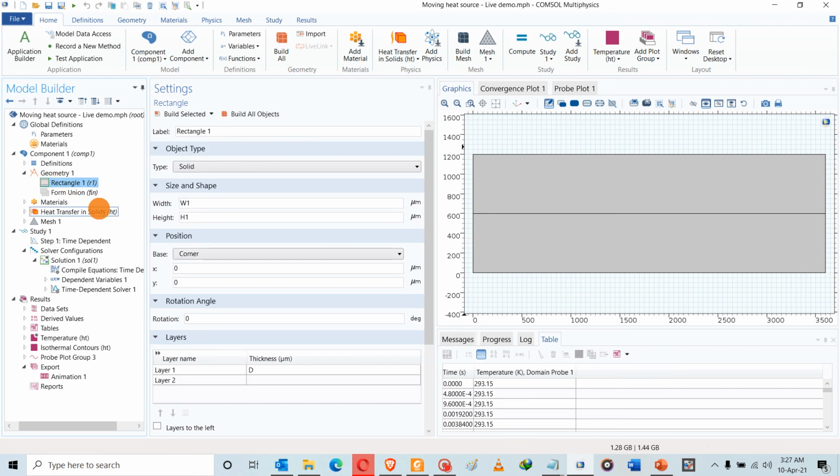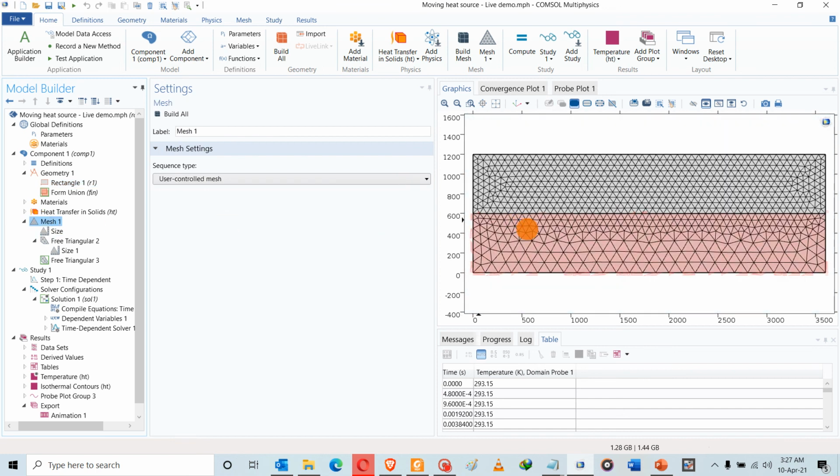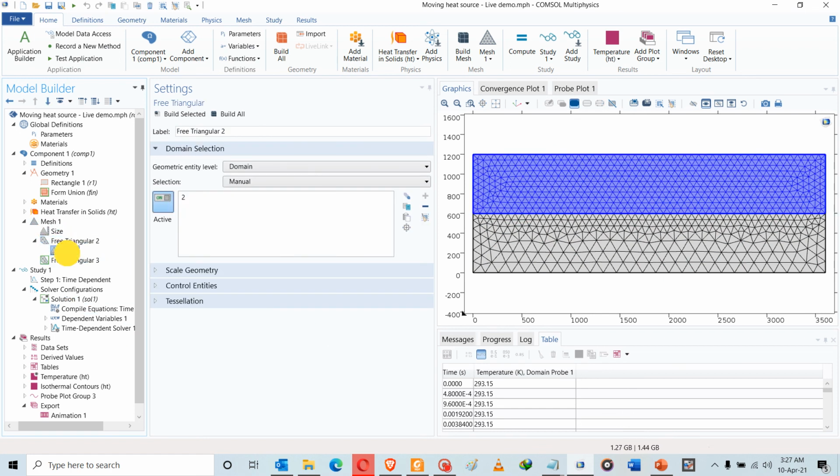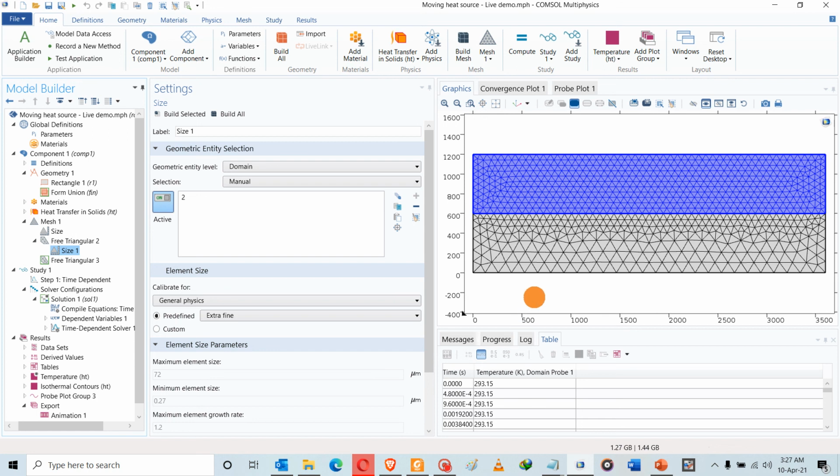And then this was our sample. We created two layers, where the top layer is highly meshed, and the bottom layer is not as highly meshed, with a coarse mesh. We had to modify this mesh from a very fine mesh into a coarse one to have a much quicker computational time. So in a way, this is a way of knowing if the model works.